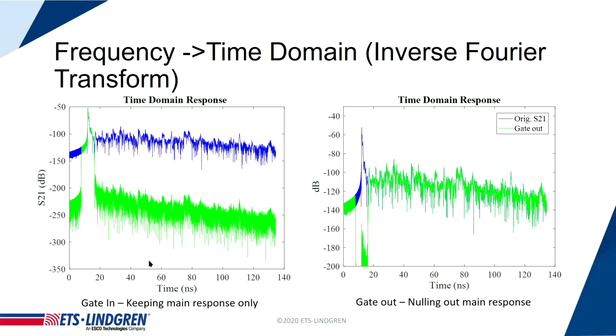Any reflections are going to happen after the main antenna response, because the main antenna-to-antenna response is the first thing, with the closest distance. All the reflections have to come from a farther distance because they need to bounce off something and come back to the antenna. So the first impulse you can see on that graph is really the main antenna-to-antenna response. What we're interested in for the time domain method is the response as if all the reflections don't exist.